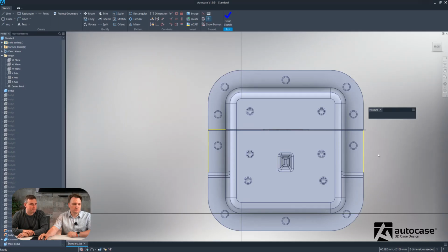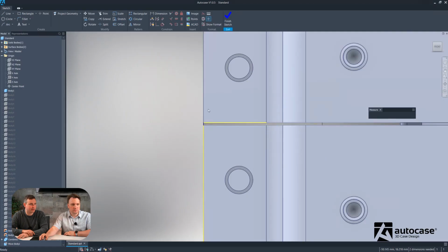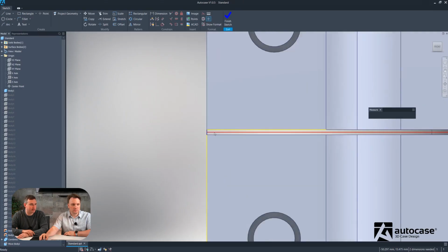the latch. Some latches won't have that on the 3D model. So depending on how you want to do this and how you want it to visually appear, we would generally recommend around about a 0.5 millimeter gap. You can do less if you like, but it just means when you do your render or drawings, the latch actually visually looks better. As you can see, the top and bottom sections catching the light and that sort of thing much more effectively.